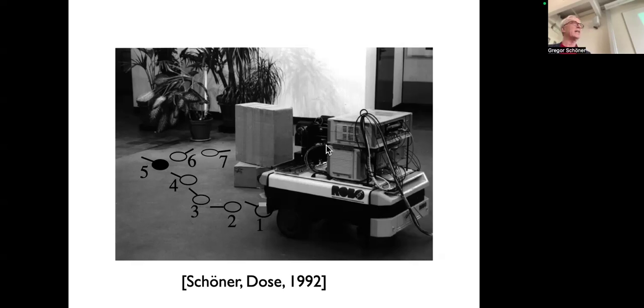Someone got a patent for that. It was never then used because better sensors arose. This would be just with vision sensors. So in any case, that's how it was done. And it had an idea about the target position from dead reckoning, that is, not from a map. You would give it its target in terms of its initial position, like 3 meters to the right. And then it keeps estimating where it is and makes errors as it does that. And that's very typically how the target acquisition works in most systems.